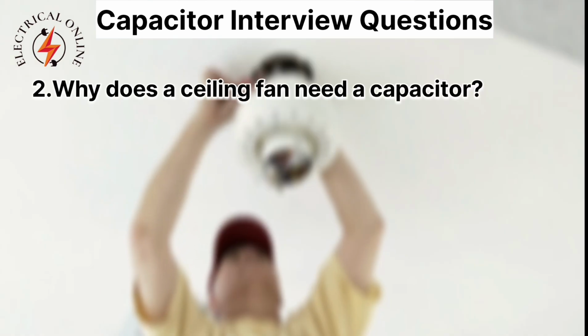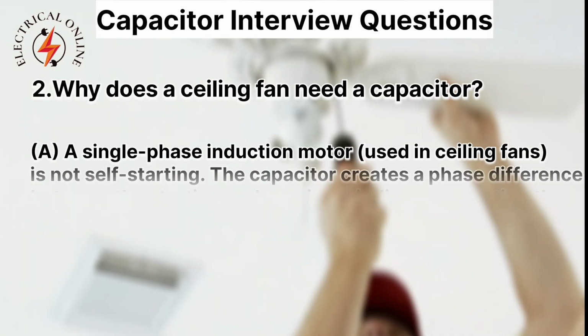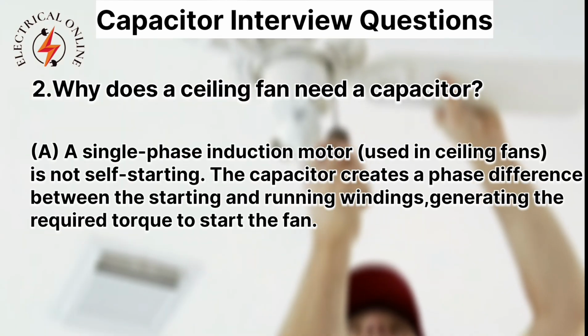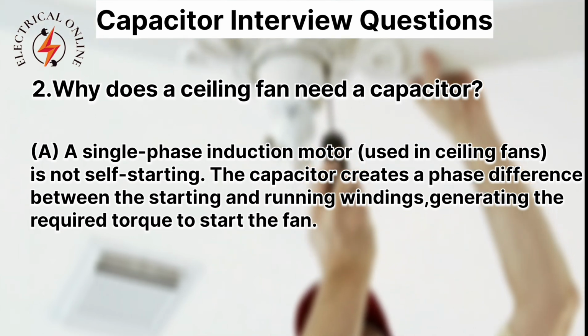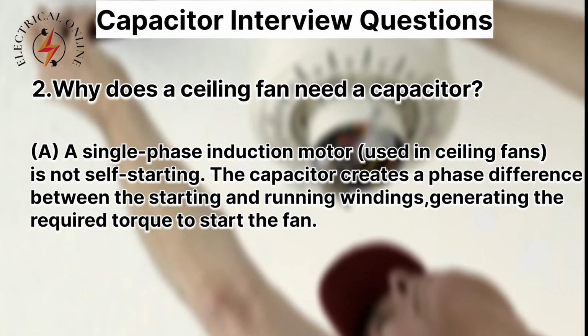2. Why does a ceiling fan need a capacitor? A single-phase induction motor, used in ceiling fans, is not self-starting. The capacitor creates a phase difference between the starting and running windings, generating the required torque to start the fan.